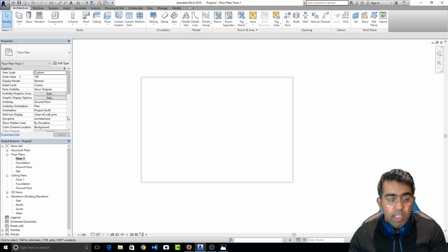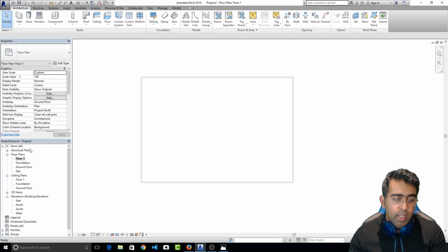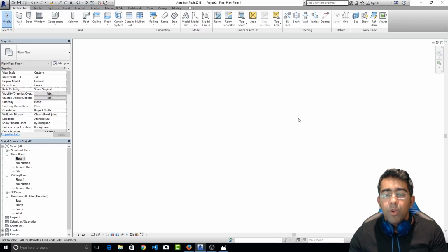So what I've done is I actually created a short video as well, but I'll show you quickly. Now if you are in level 1, here you have an option for underlay. Okay, underlay. So here if I click on none and I click on apply, you won't see anything now. Now you don't know where your ground floor or your ground plan is.